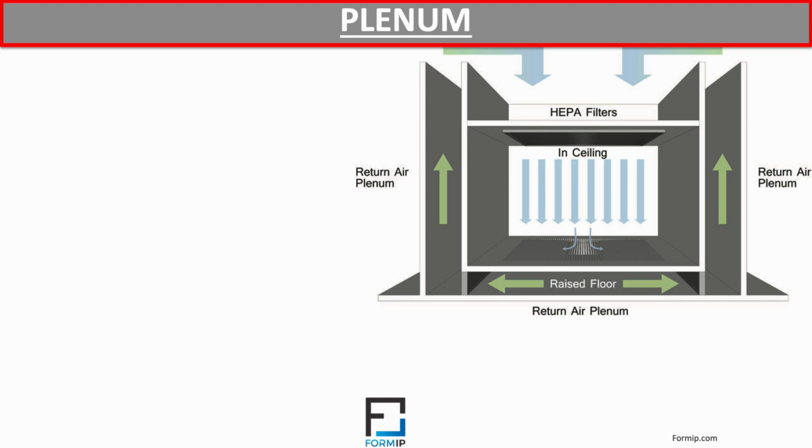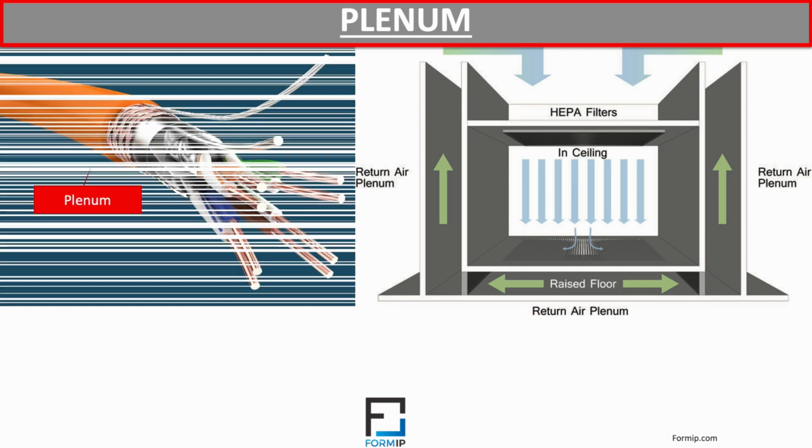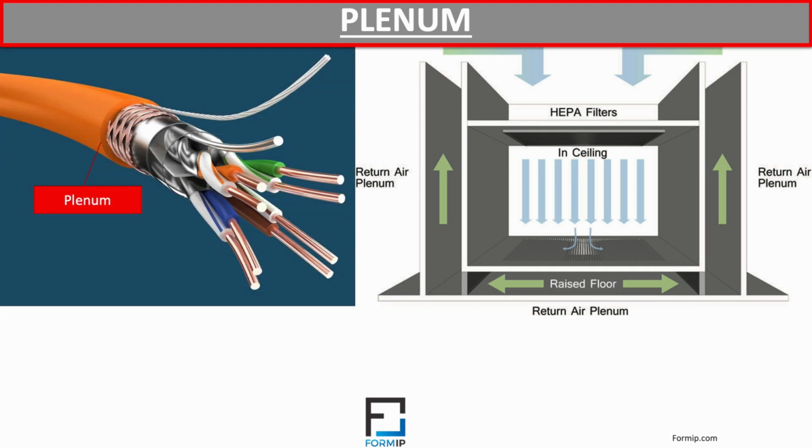We are now going to talk about a technical term, plenum. Some questions on the CompTIA exam are about this name. The plenum type cable is an electrical cable that is laid in particular areas of buildings. In the USA, the plastics used in the construction of plenum cables are regulated by a standard for the installation of air conditioning and ventilation systems.